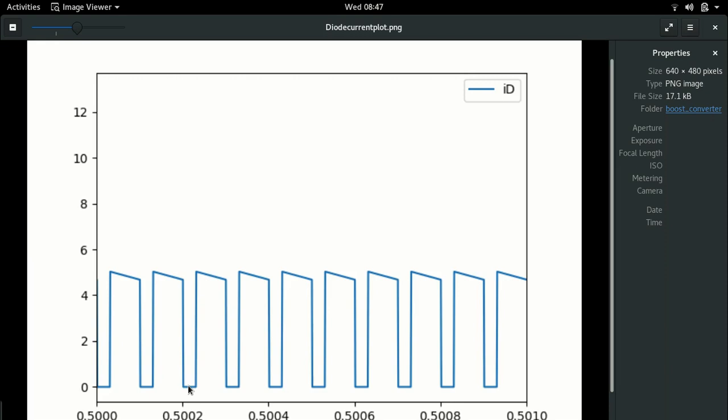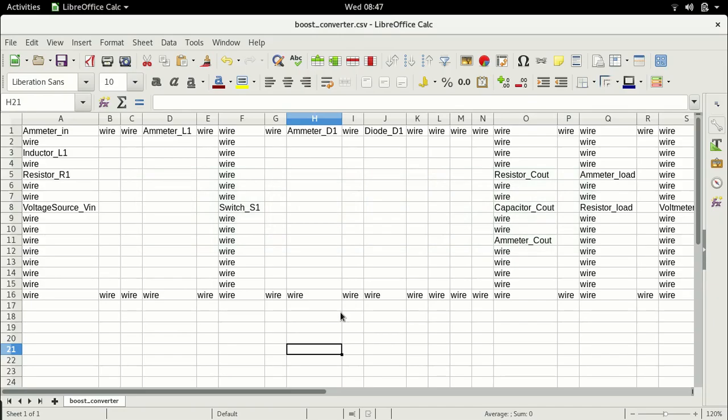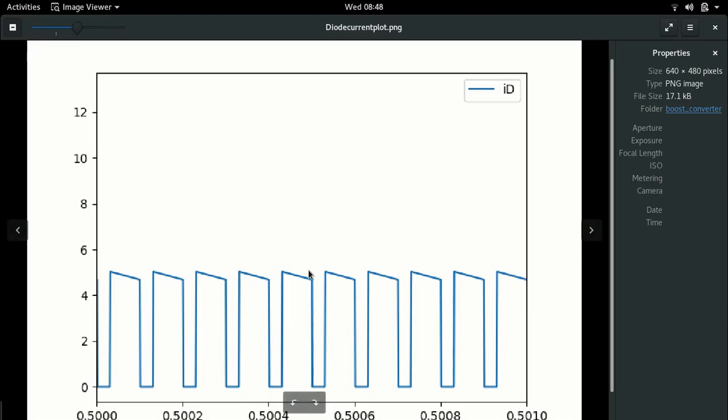And since this output voltage is greater than the input voltage, because remember this is a boost converter, the output voltage is greater, the diode is reverse biased because there is a greater voltage on the cathode than on the anode. The result is the diode is reverse biased and it cannot conduct a current. So the capacitor cannot discharge through the switch through the diode. The diode is reverse biased. It will not let the current flow. So this is why you have current flowing only when the current is falling through the inductor, right?